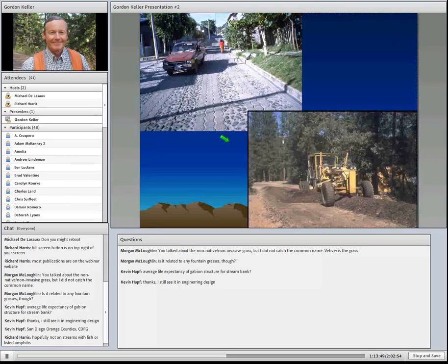Here you have a couple other alternatives. This is a combination of both these pavers and some cobblestone used in some places in the Southwest. It's very labor intensive, so that's why you see it a lot in some developing countries, not so much in this country. Then there's road mixes, which was the old style of creating pavements. I've done a few jobs with them, and you can save some money over hot mix asphalt, but then there's more quality control issues. So it's not a technique that's used a great deal today, but it is an option.